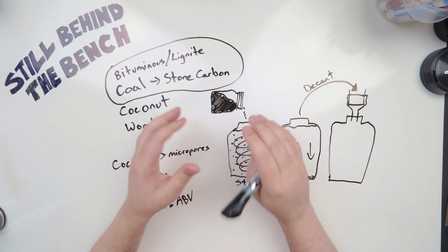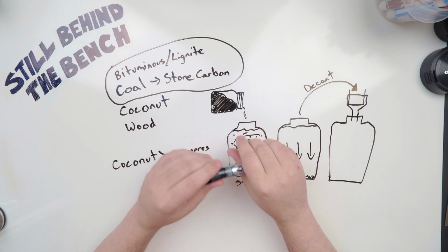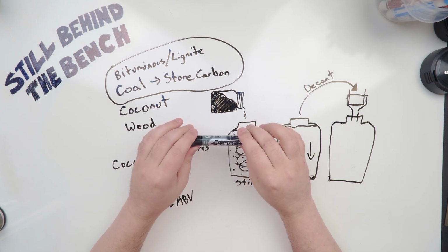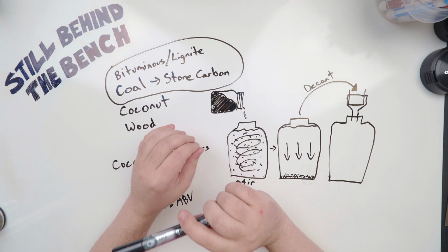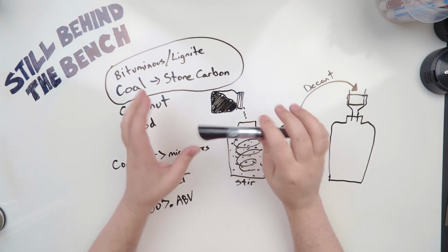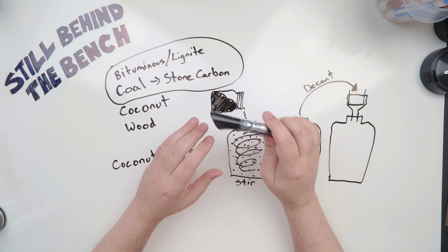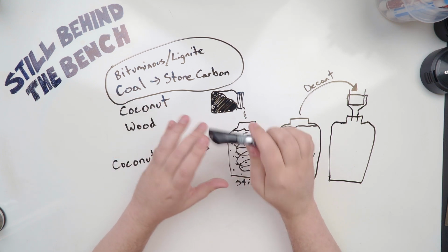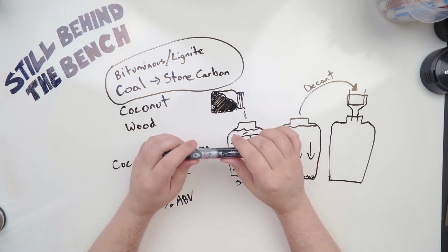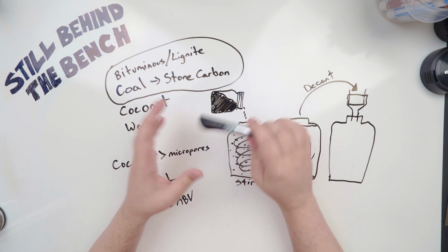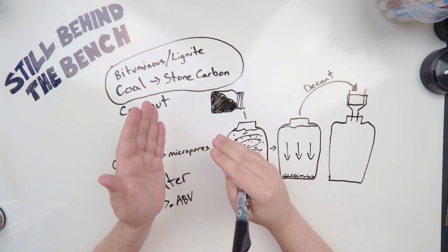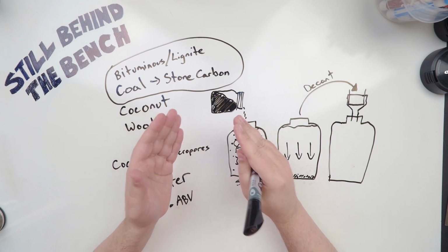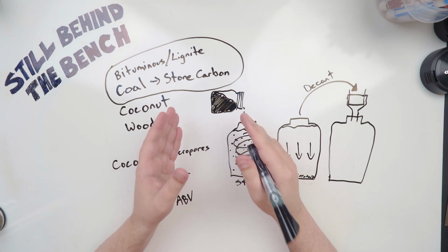The last main thing I wanted to talk to you about was pre-wetting. You'll see it mentioned on all kinds of forums. I imagine some distilleries also do it if they use a column-based filter like that. Pre-wetting is done in industrial chemical facilities. It's done in water treatment facilities. And they do it for a few reasons, all of which are related to pumping, process time, channeling, and safety. So not pre-wetting can significantly impact the efficiency of a pumped filter.